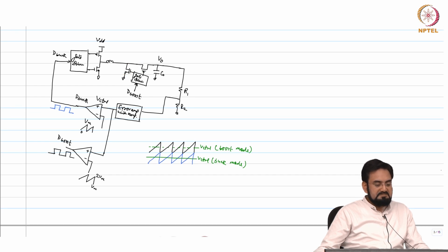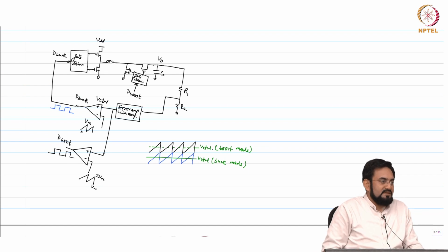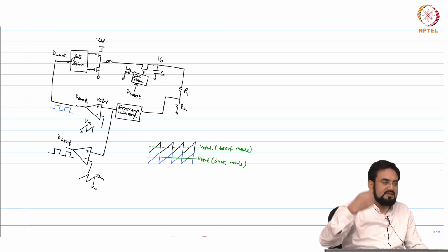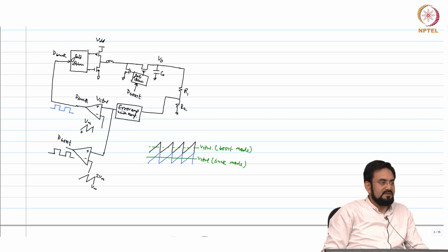Okay. So if you don't have any limits on the duty cycle, it will very smoothly go from buck mode to boost mode. There is no buck-boost mode as such here. Okay. There is no condition where all the 4 switches will be operating, because your maximum limit is here 100% and your minimum duty cycle in case of boost is 0%.